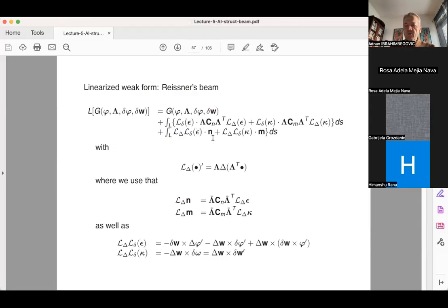And that's why you have this contribution. And then you have, let's say, the derivative of the virtual strain in terms of bending. And then the second part would be the material part. We have this contribution from a virtual strain and the incremental strain, both for the axial and shear actions and the bending.